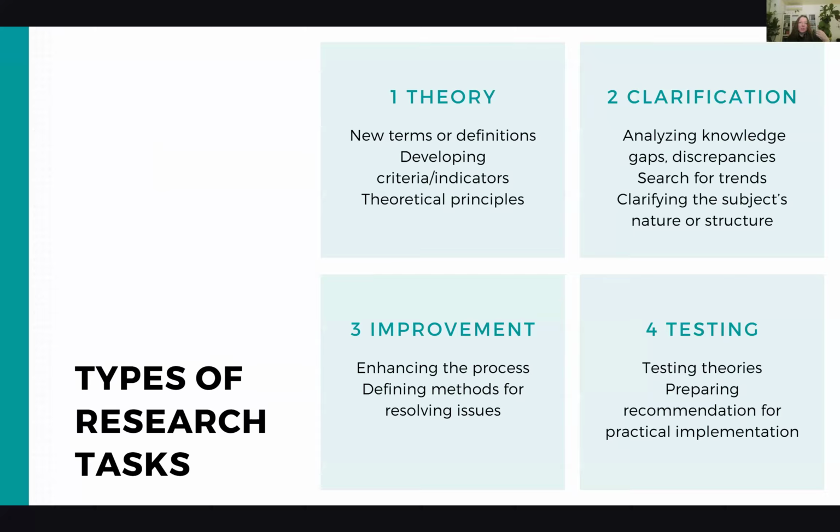And you can suggest improvements, for example, by adjusting your gating system or by adding some other components to that system to remove those shrinkage defects. So that would be your improvement. And testing would usually imply some sort of experiment that checks your improvement and helps you check whether they work or not. So, do they solve the problem or not?